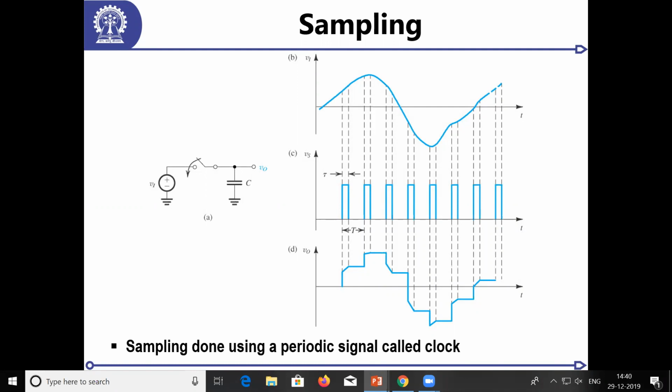Let's put in some margin. Designers and engineers always put in margins. That is very, very important, otherwise things won't work. So you have to put in margins in every design. So let's go for 7 time constants. I won't go into the math, but there is exactly an equation which tells you how many time constants you need to sample a signal depending on the sample rate.